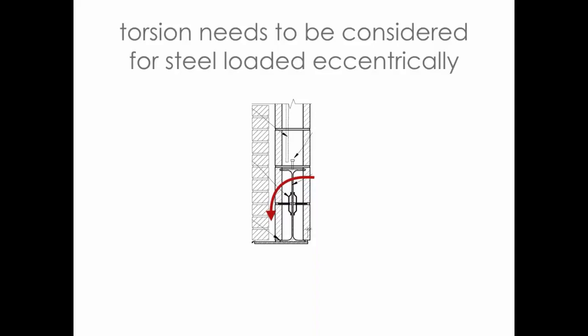But the torsional loads on a steel lintel are not easy to resolve. If it's a wide flange, we have to add a lot of stiffeners. Then we have all the stiffeners that we have to cut all the copes and all the different elements around, because wide flanges don't work well in torsion. So any types of loads like this, we have to start to account for. So there's problems, there's issues that we have to somehow work to resolve. And if, again, you get into that 1% scenario, I'd be really glad to help you solve the different issues that you have with the steel lintel.